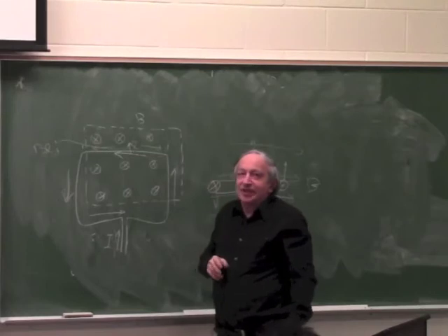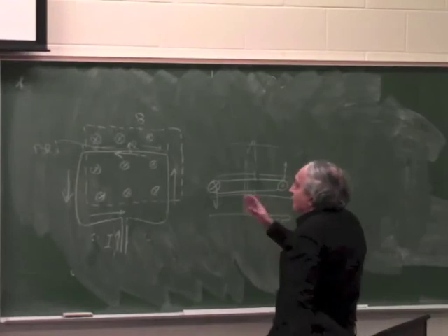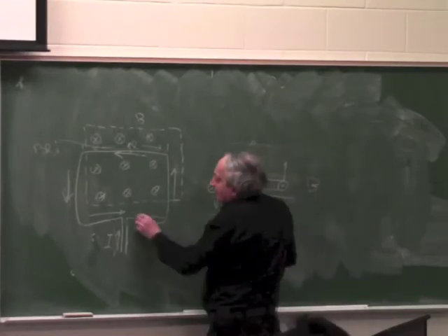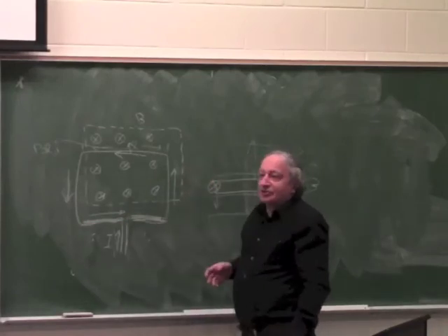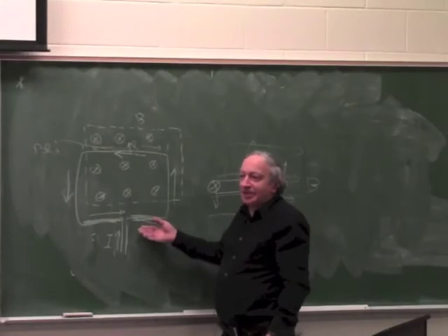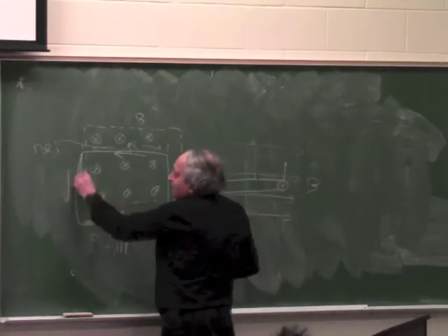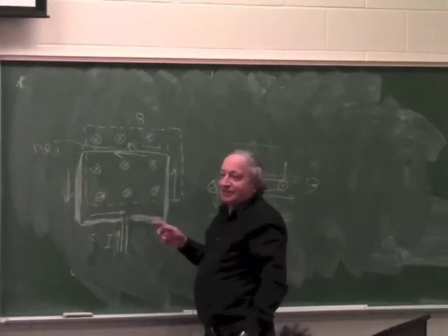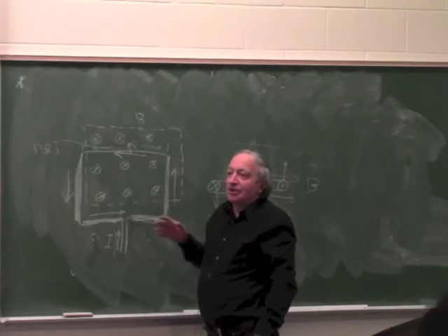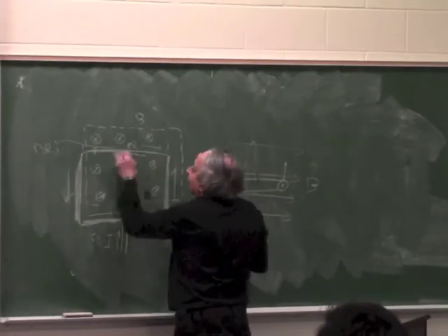And this shows you already the first problem with moving coil actuators, because if I look at a loop like this, this part has to be outside the field, otherwise the force will cancel out. So this part adds weight to the actuator but doesn't do any work. But I have to have it because I have to close the current path to a loop. Now these two parts add weight but create opposing forces which cancel out. Basically the only part of this whole loop which creates a force is this part.